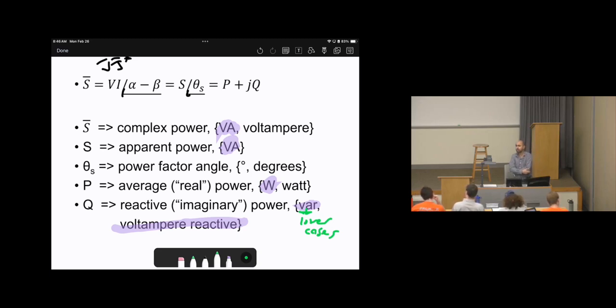Or even, when we pay for the utility, since our electrical circuit is AC, not DC, do we pay for real power? Do we pay for reactive power or complex power? What do you think? Recall when you look at the utility bill, the unit is kilowatt hours, right? So we pay for the net energy based on real power, not the reactive power. Okay? So we are consuming reactive power, but we will not pay for this.